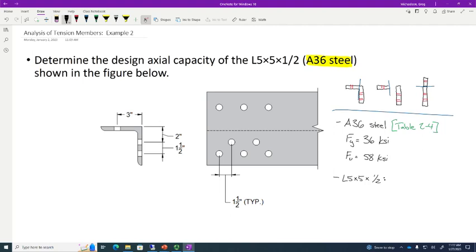Because think about it, if you have a building that's 30, 40, 50 stories tall, that's a lot of force that column has to withstand. So if you're using a 50 KSI grade of steel, that's a really big column, right? Maybe you can make that column actually physically smaller by using a steel that can withstand more stress. Okay, so that's a good example of using that grade of steel in building design. Maybe for beams and moment frames, but gravity loads under really, really heavy loads, that would be a good example.